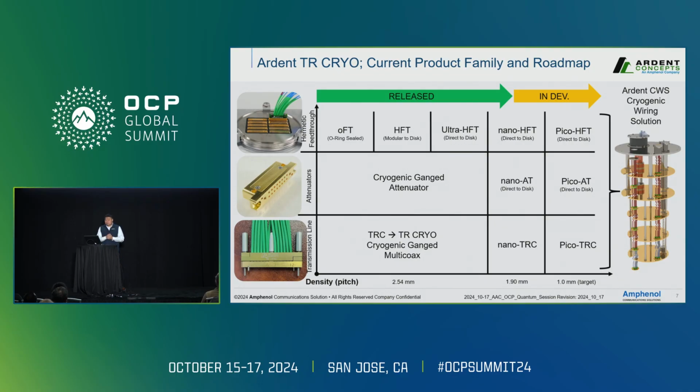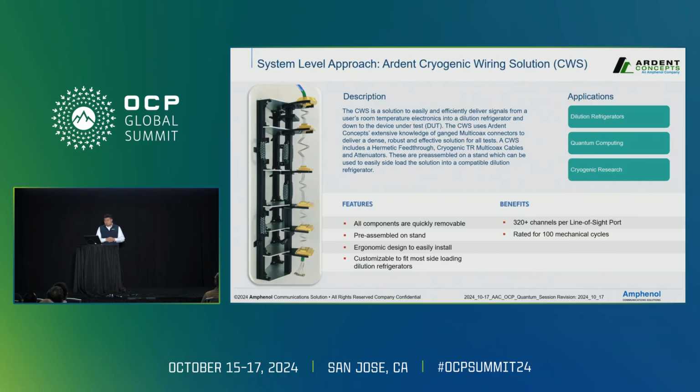And as application requirements continue to evolve, we're looking at even more microwave components such as filters, amplifiers, and couplers starting to be incorporated into this high-density GaN approach as well, just like the attenuators. The development of all of these individual interconnect components culminates in a full fridge high-density wiring system, like the example shown here.